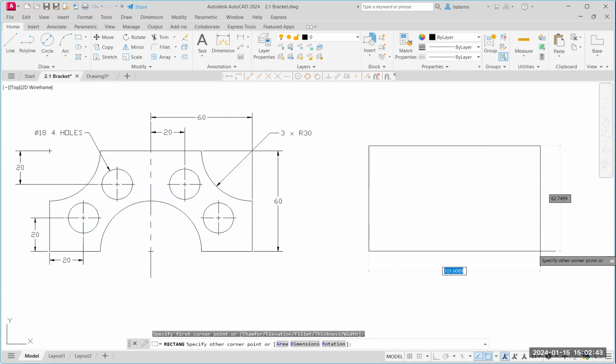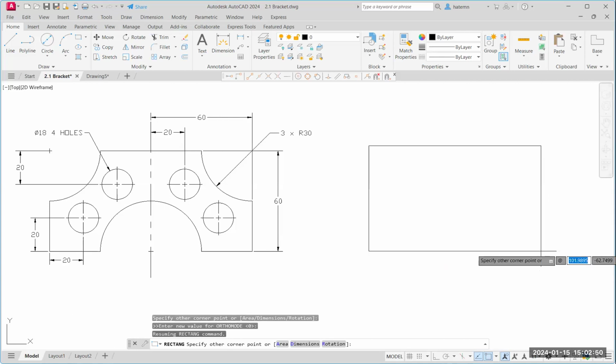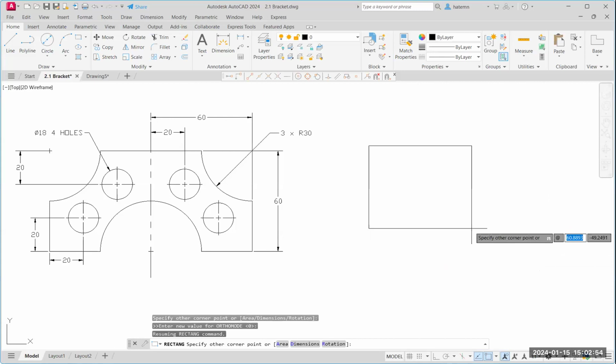The first thing I'm going to do is my @ symbol. So Shift 2, that @ symbol, because where I clicked this upper corner here, I just did a random point. So when I put that @ symbol, if you remember from earlier videos, it makes wherever you clicked a temporary 0, 0.